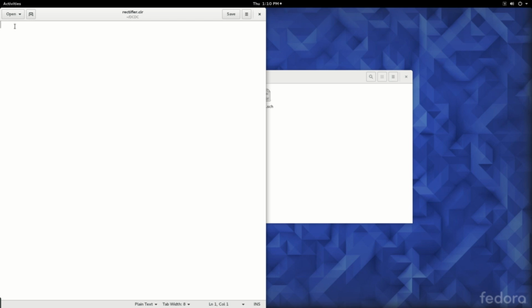And here, the first line is always a comment, so start from the second line. We would like to have a transient analysis performed, step time of 50 microsecond up to 100 millisecond using the initial conditions. Also include the rectifier.net. The rectifier.net is not yet generated, but we will shortly generate that. I will let you know how to do that.